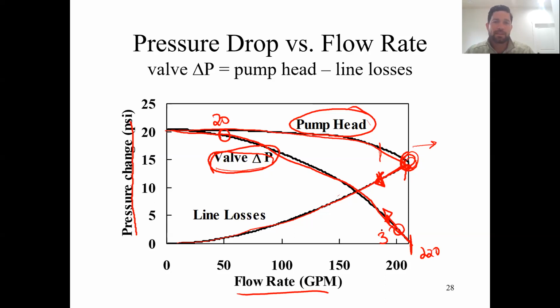An easier to use heuristic, and what you can use for this class, is if you have pump driven flow, use equal percentage. If you have gravity driven flow based on hydrostatic head, use linear. You can calculate it and make a decision, but generally, if you have pump driven flow, you're going to have this type of behavior. If you have hydrostatic head, you can use either one of those metrics to determine which one you use.